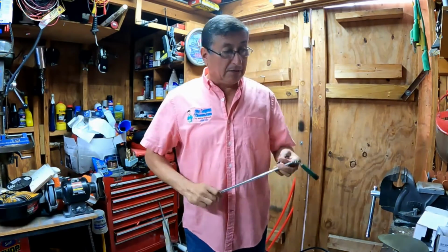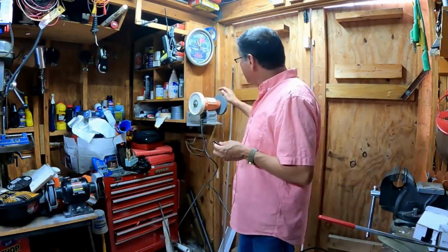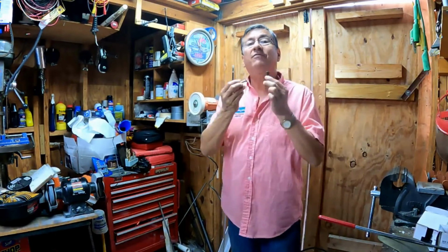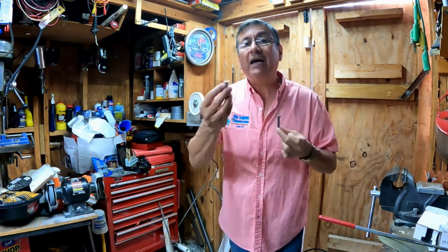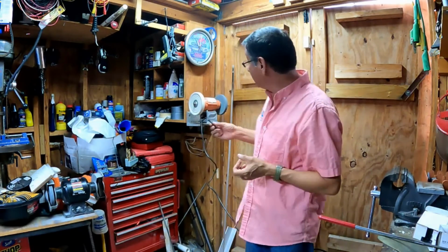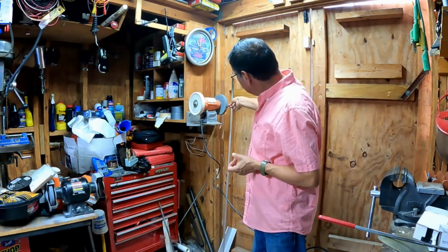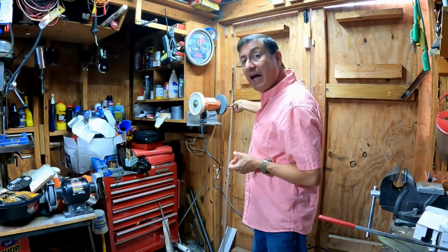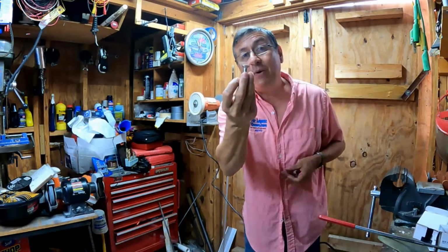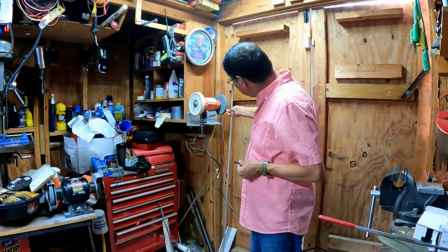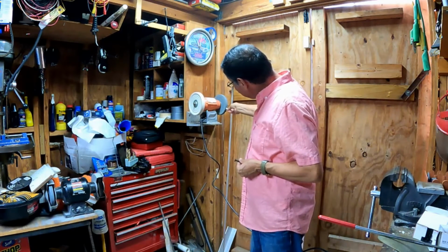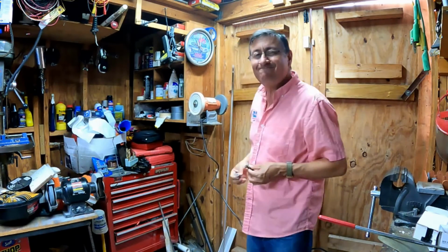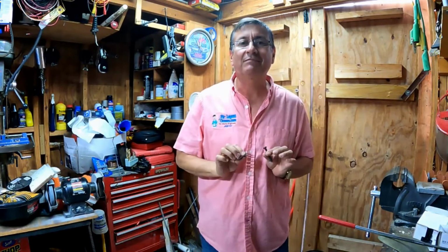This is with the magnet. But also with the grinder, you can verify if the steel is marine grade. This is a regular steel and this is stainless steel, marine grade. The regular steel produces a lot of sparks with the grinder. And this one, the stainless steel, practically nothing.